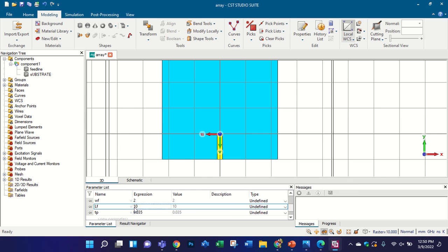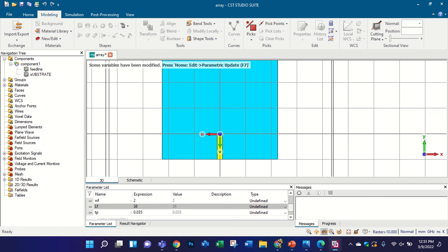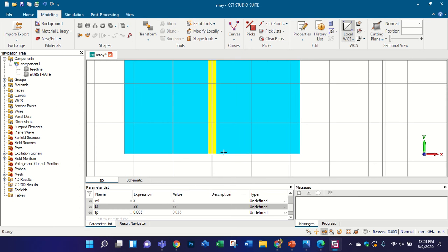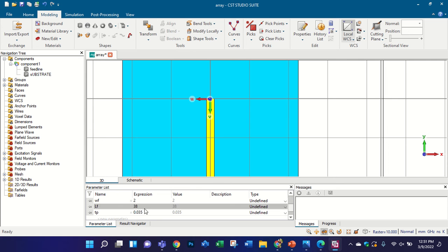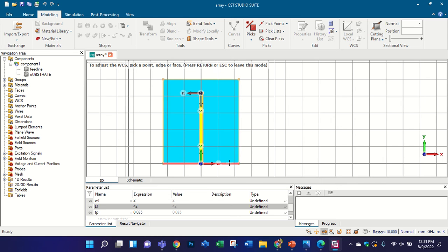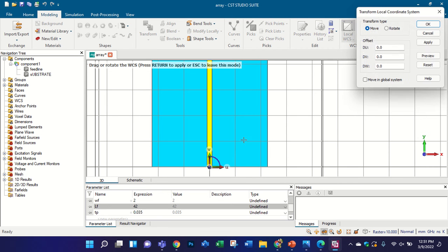So it must start from 50 if you want. It depends on the resistance of the antenna. If the resistance of the antenna is more than 50, we must graduate it from 50 up to the resistance of the antenna. If the antenna resistance is less than the transmission line, we must reduce it. So this is the way for the Chebyshev and the binomial theory.